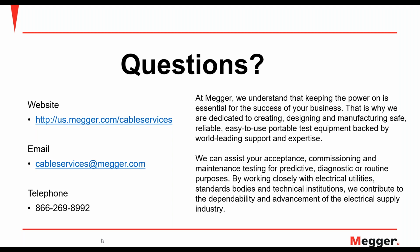Thanks for the question, Michael. Damped AC, or DAC, is a waveform used for partial discharge testing, so you really wouldn't use it for your tan delta measurement. That would be your 0.1 Hz sinus wave. As far as cable capacitance, typically the measurement systems will do a pre-check of the cable and determine that capacitance. So even in the damped AC mode, you'll still get the capacitance of that cable. But damped AC is typically used to identify and locate partial discharge within a cable.